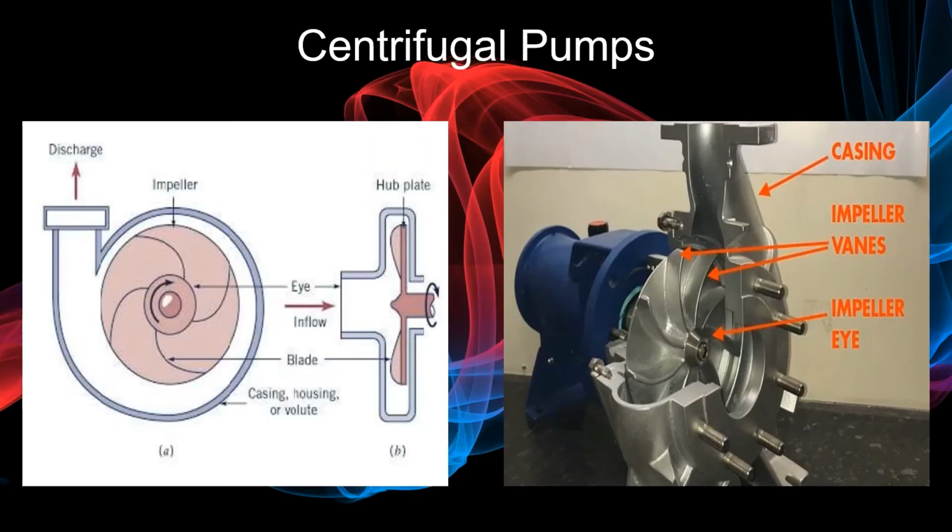Hi, Josh Grunden here, and now we're going to cover our first turbo machine, the centrifugal pump. Our centrifugal pumps are low capacity and high head pumps. This means that they have a low flow rate, but result in a large energy change in the fluid, mainly in the form of pressure. The centrifugal pump is our most common radial flow turbo machine.